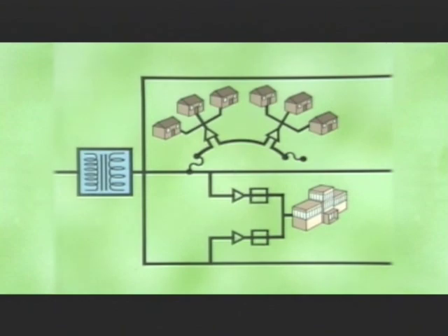In a loop design, the lateral coming off the feeder runs through a region of the service area and has the capability of rejoining the feeder farther down the line. This is very common in residential communities that are supplied by underground systems. The lateral is connected to the feeder at one end by a fuse. At the other end of the lateral, there is also a fuse. This connection is often left open. With this type of layout, power can be supplied from either direction, depending on which fuse is opened and which fuse is closed.